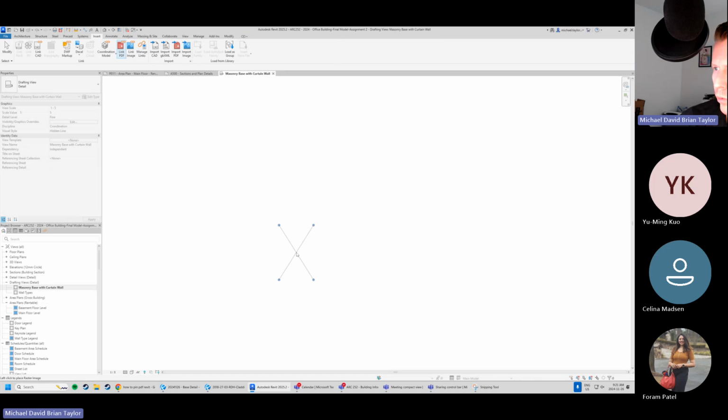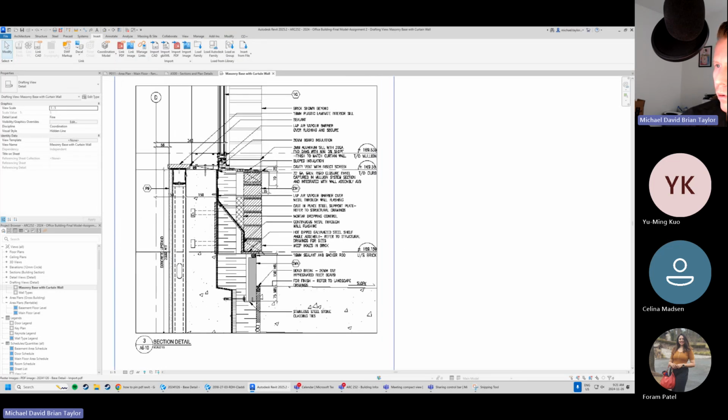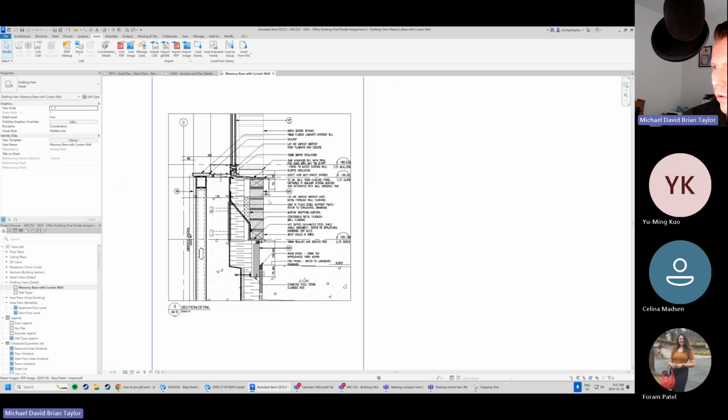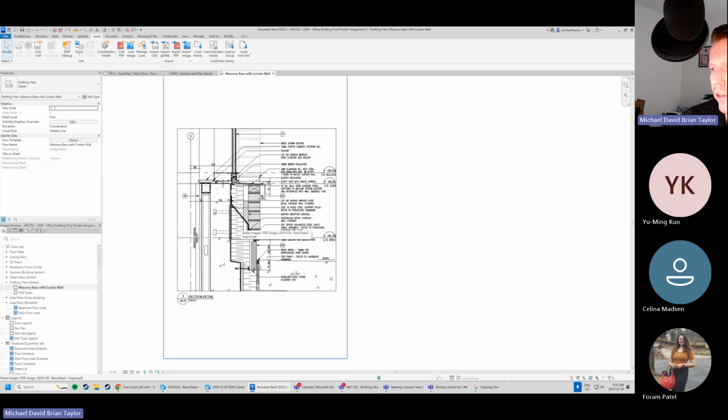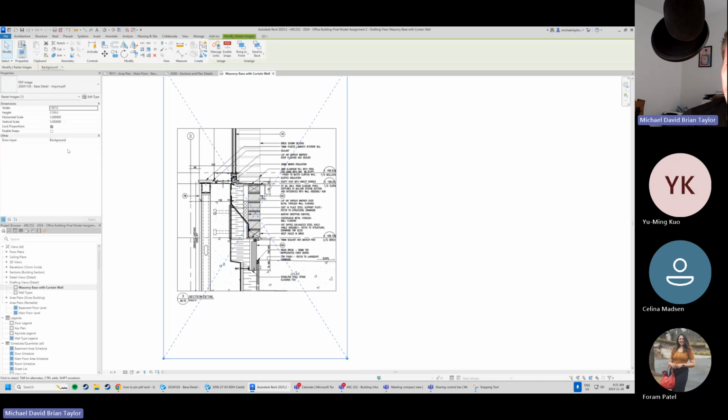It can be anywhere, as there's no geometrical link back to the model. So it can be anywhere in this blank space. Let's click once here, and you might import it and go, what the heck did I do? Why is it like this? I can barely read anything. That's because you may have missed that one step. We can't change the dots per inch in this phase, so what you would have to do is relink that file.